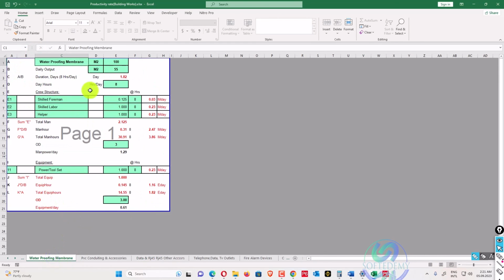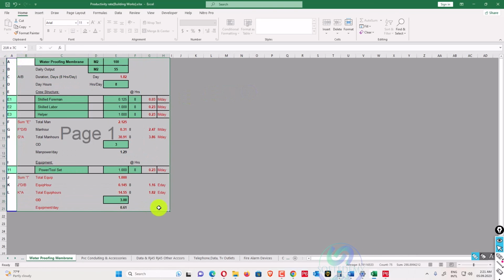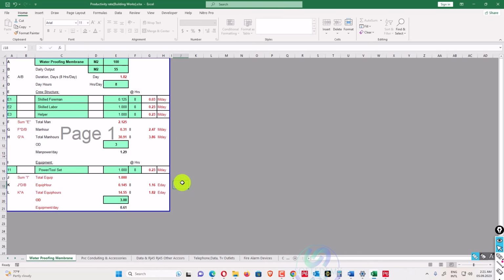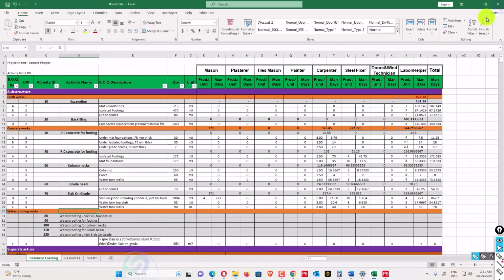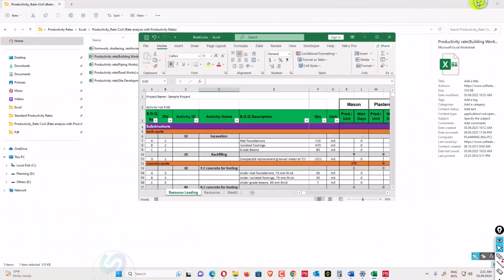If we have a waterproofing membrane, we will utilize that. So we can have an accurate cost, and as per our rate analysis, we have accurate manpower. This is manpower, this is their crew ratio, and this is the quantity of work they will do in 8 hours. It's similar to the sheets I explained to you, so you will check this sheet and also understand from there.